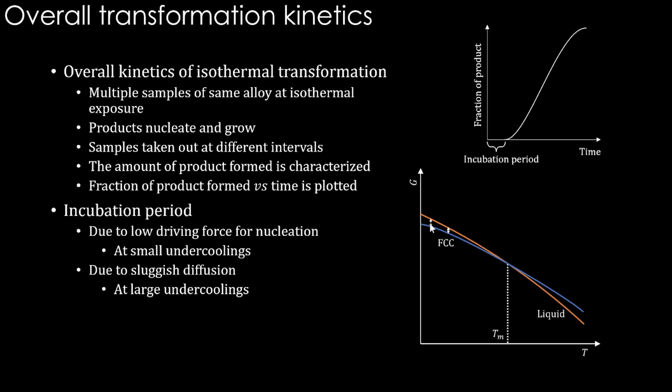If you remember that capital D, the movement of atoms in the parent and in the product, especially across the interface, these diffusivities are going to matter, and they are going to be very low if you go to a very low temperature. So there should be some sweet spot undercooling, where the nucleation rate, growth rate and all will be optimal.